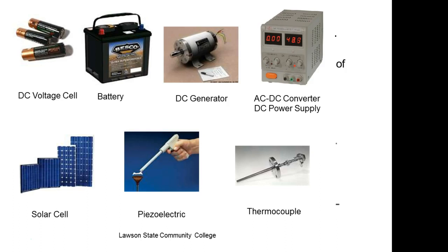Those are actually cells. If you're old enough, you might remember why they called them cells. But now everybody started calling them batteries because of the batteries in cars. To get a battery, you got to have more than one, right? You understand that? So we create batteries most of the time with cells. When you put these things in, you usually hook them in series or in parallel. We hook them in series to increase the voltage. What advantage does a higher voltage have? Yeah, power with smaller conductors, right? You understand that? And then what happens if we hook batteries in parallel? We add current.